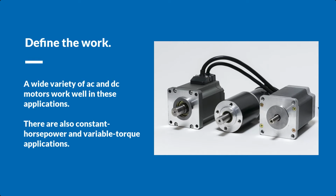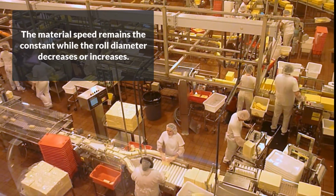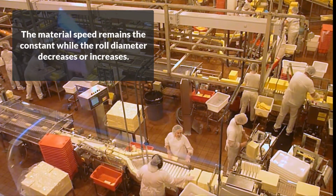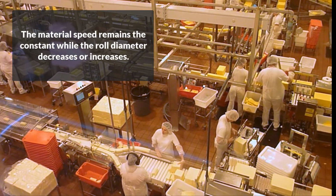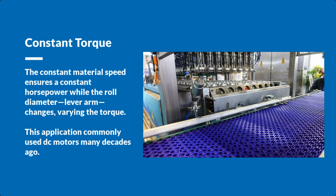There are also constant horsepower and variable torque applications. A simple example of this is an unwind or rewind application. The material speed remains constant while the roll diameter decreases or increases. The constant material speed ensures a constant horsepower while the roll diameter, lever arm, changes, varying the torque.